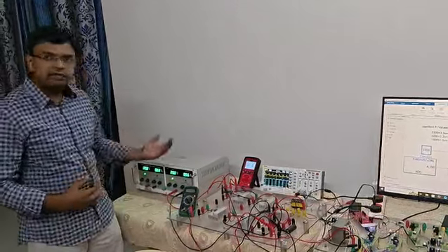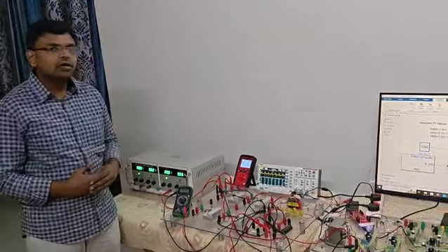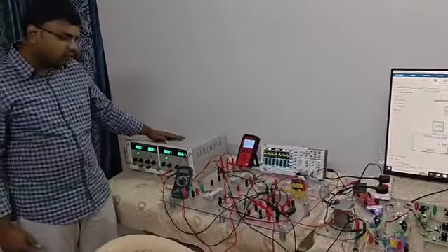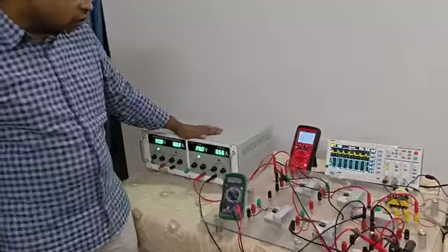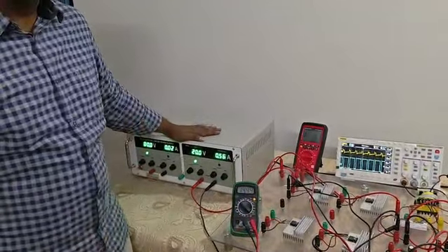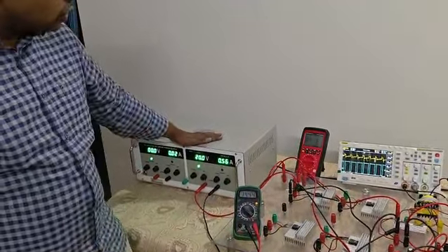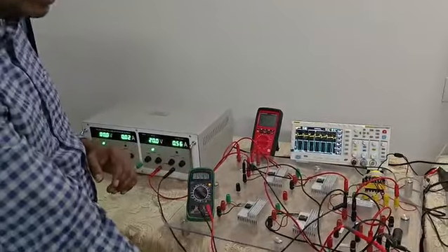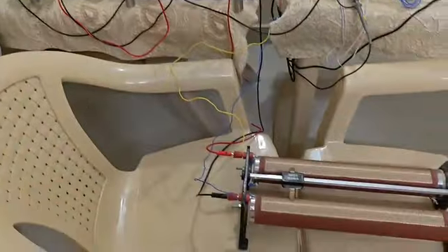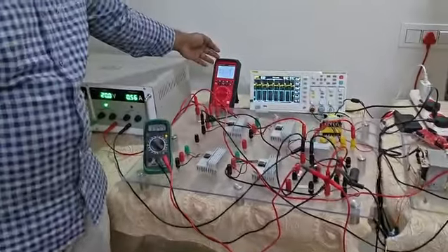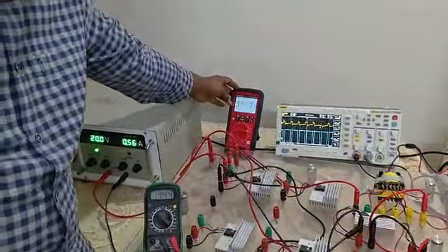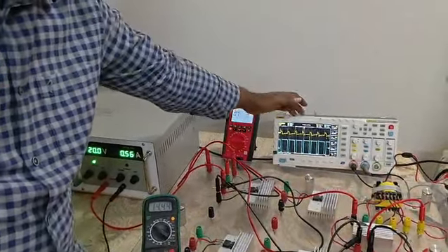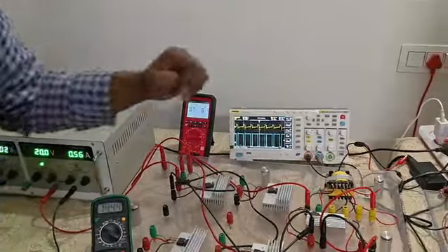Now, the hardware I am showing with the help of the ADC channel. First, we have set 20 volts here to overcome the problem of the ADC sensor. The output voltage I have now set to 15 volts using this rheostat, and this is the high frequency multimeter. The current I am showing presently is 0.7 amps, right? And this is a duty cycle of 77%.